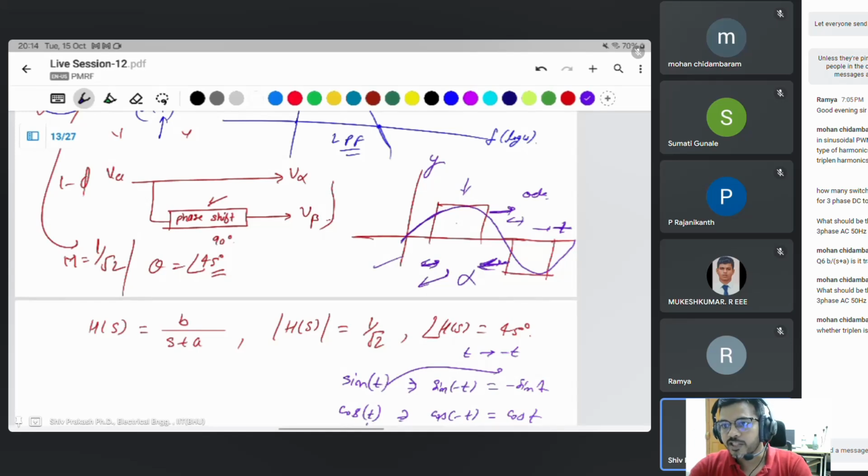And in space vector modulation, if you try this one, then because of using a three phase system, third harmonics, multiplication of three, are eliminated. It means the same thing, odd harmonics except the triple harmonics.